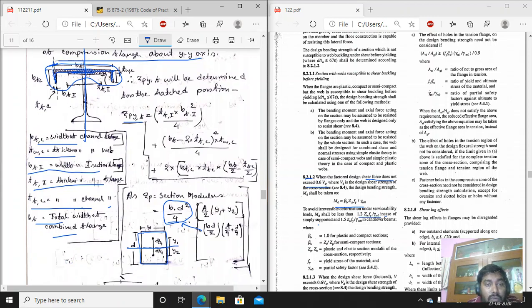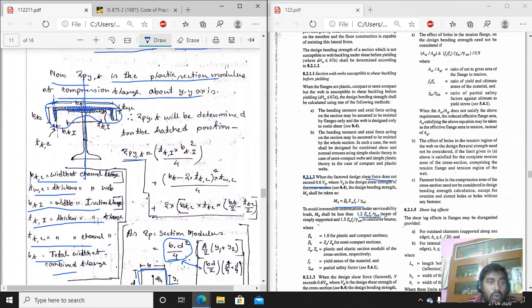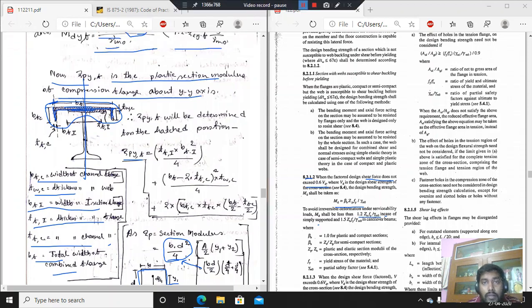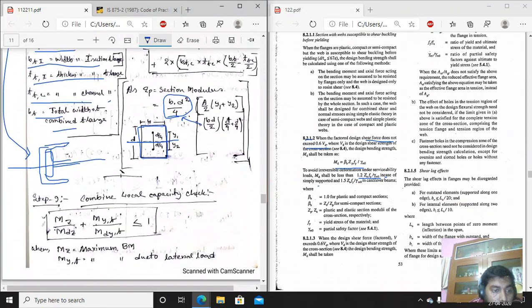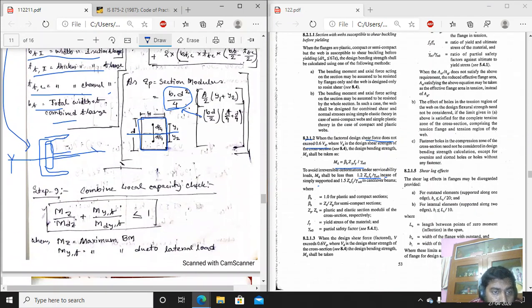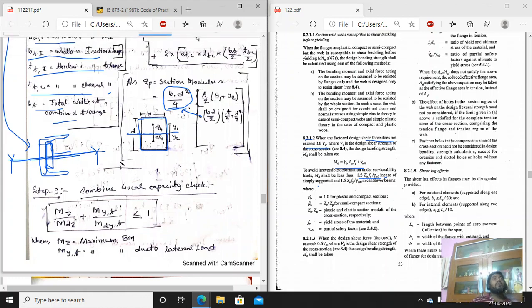Here I have drawn this member like that. So this is the YY section. You can see that for this web member and this flange of the I section, the YY axis passes through the CG of that section. So we do not need to determine the equal area axis here, because we know what the equal area axis will be.